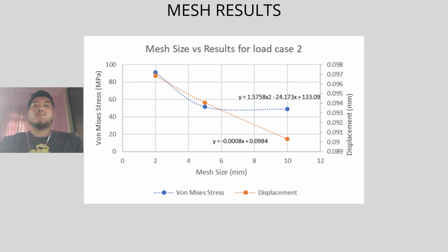Besides, from the graph also we can see that when a smaller mesh size is used, the greater the maximum stress and displacement. Hence, a fine mesh provides more accurate results for this case.